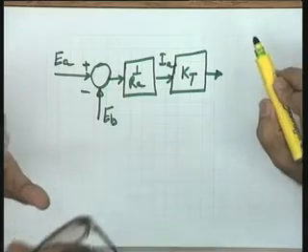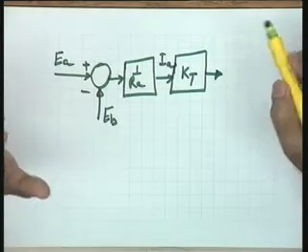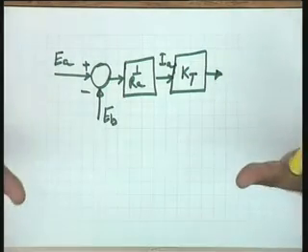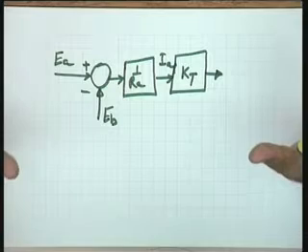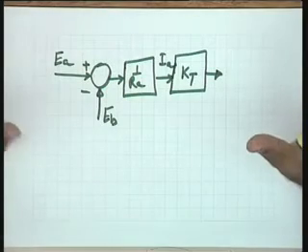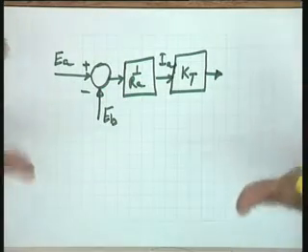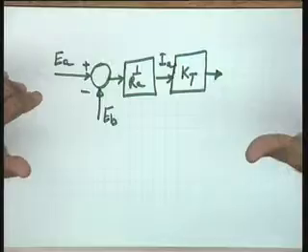Can you help me here? What should I do to proceed further? Now, I have got the torque produced by the motor, it is Ia into Kt. Now, what is the net torque which is available for driving the inertia? It is not Tm, it is Tm minus Tw.